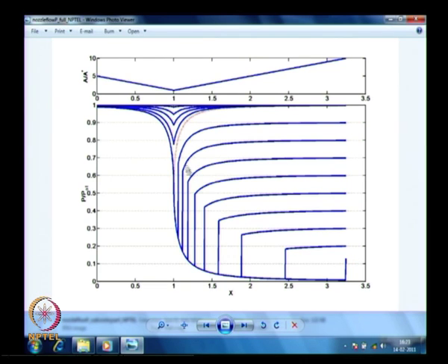So if you see what is happening, I have plotted for a linear nozzle, a straight line nozzle. This curve does not change beyond that point. The subsonic part does not change. Why? Obviously this point gets choked, and whatever happens downstream, nothing gets affected upstream of that Mach 1 condition. This is the choked condition, nothing upstream changes beyond that point. So this curve is the same for all these curves, starting from this red dotted line all the way till all these curves to the left of x equal to 1 is all the same. Every curve is one on top of the other.